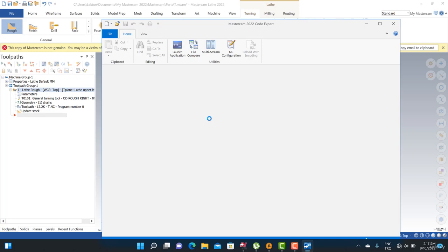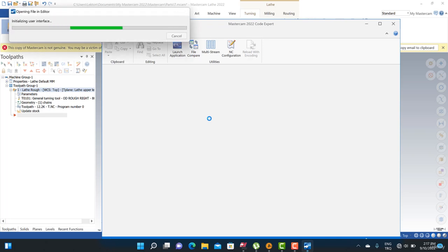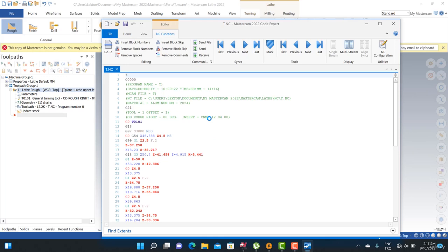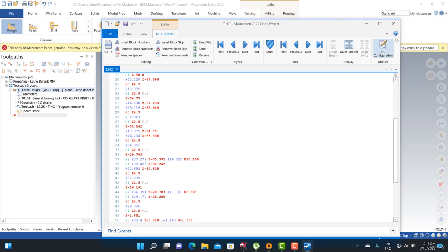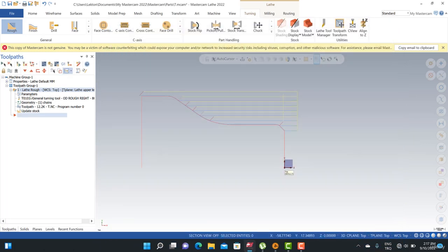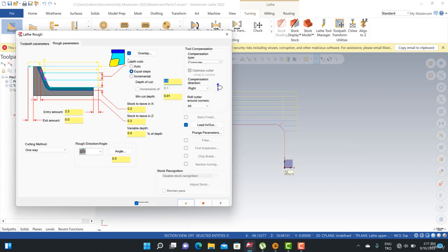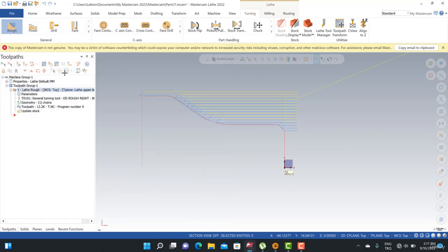So at that point, maybe when I turn to my CNC machine, I can figure out that my step down is not good. So I need to change that. So I need to turn back to Mastercam and click the parameters, and then this is my depth of cut parameter. This is 2 mm, so I can change that here. Okay, I can make it 1.